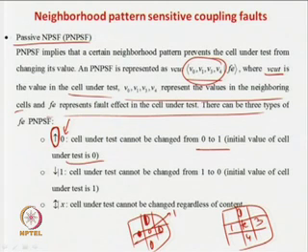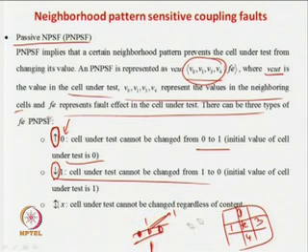all these are now 1, 1, 1, 1, and this is also 1. Now, you want to make this 1 go from 1 to 0, that is, you want to make it fall, but because all the other peripheral cells are 1, you will not be able to do that. So, this is another kind of neighborhood pattern sensitive fault which is passive in nature. All these are 0 or all these are 1s. So, passively they are trying to hold the value of the other neighboring cell which is being affected.